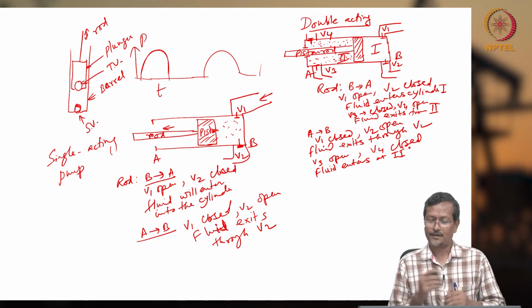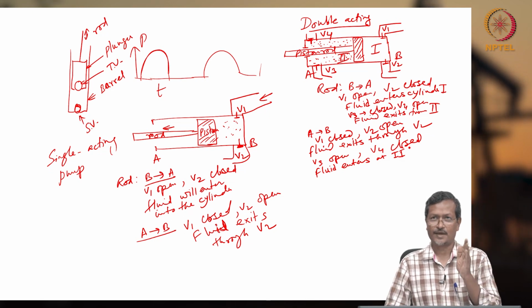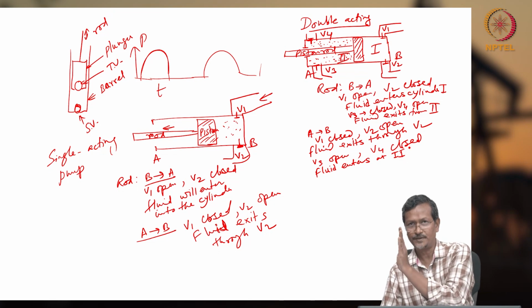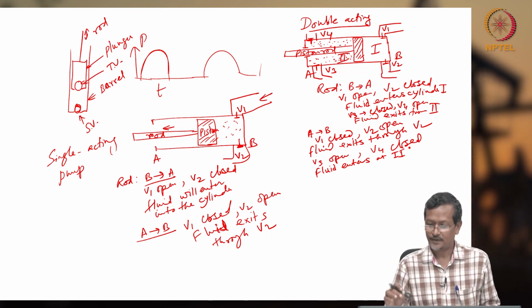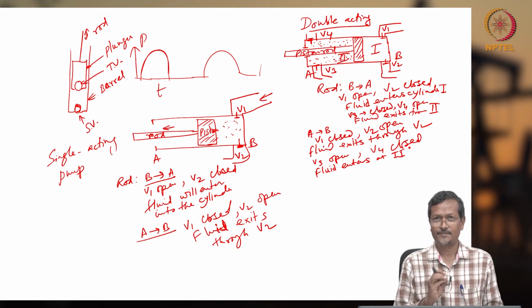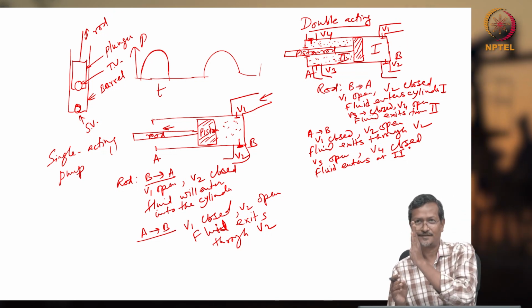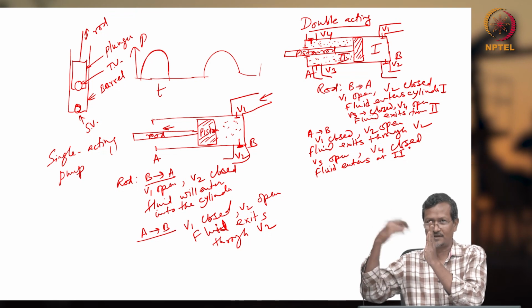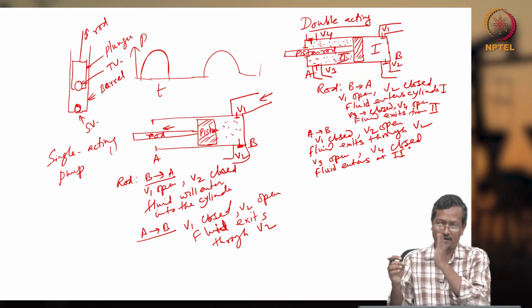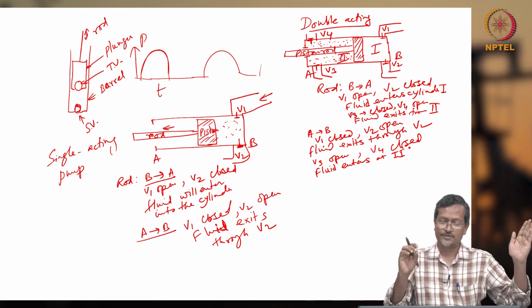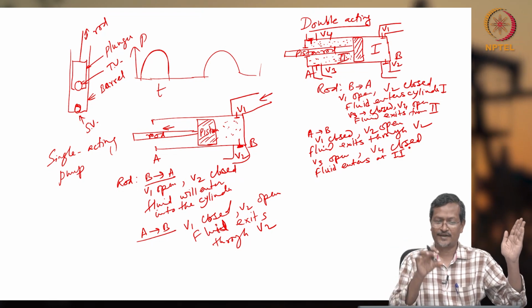Okay, the A to B sequence is happening, piston moving A to B. So at that time fluid is entering into cylinder 2. So now you see, when the piston is moving left to right, one cylinder is delivering, one cylinder is taking fluid, and the opposite. So again the same thing is happening, one taking, one delivering.